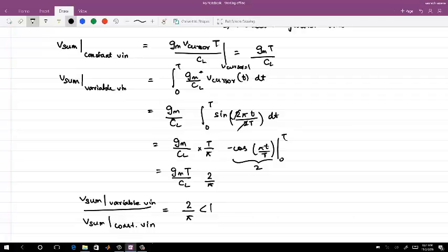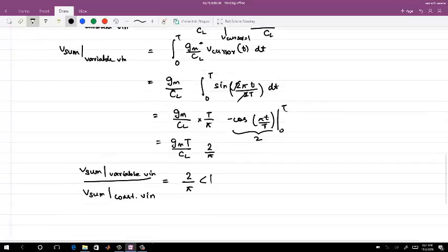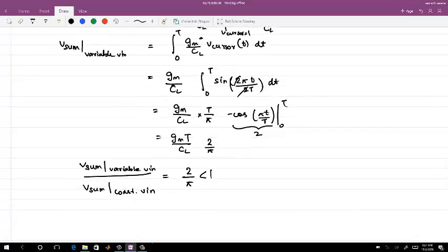So this is just for the integrating type, because we have not done this analysis for a variable Vin in case of your regular RLC or settling type, but there also this thing will appear in the picture. But I'm doing this for integrating type because for the integration I just assumed the V was constant. Okay. So it says that the integrating type DFE has a frequency dependent gain.